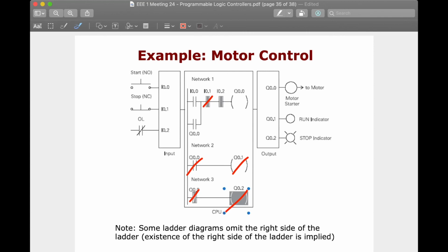But when the motor is running, so that means when this one is on, this one becomes obviously low, and so you normally attach a NOT operation here, so that means this becomes off. Okay, so it is again by default shorted, and this is by default turned on. Now when you start the push button, this becomes high, so it becomes the NOT of this, so it becomes low, and so that's for this regular motor control.